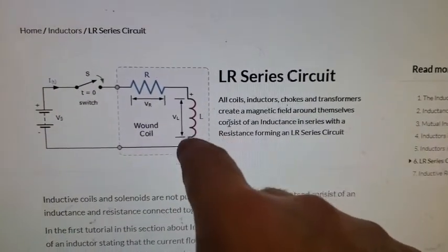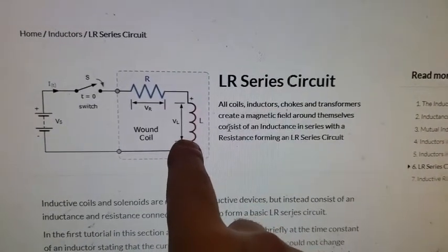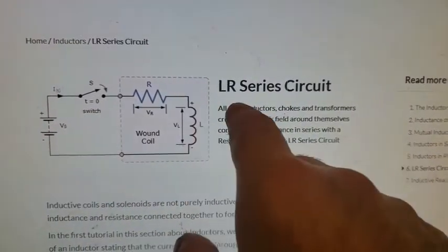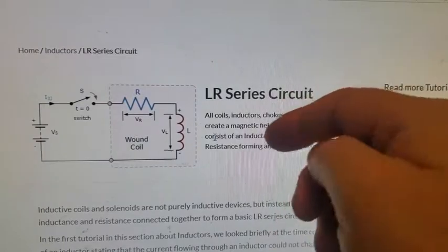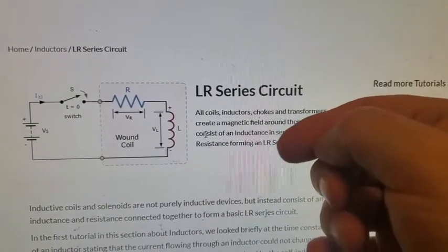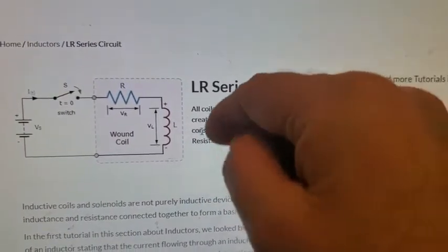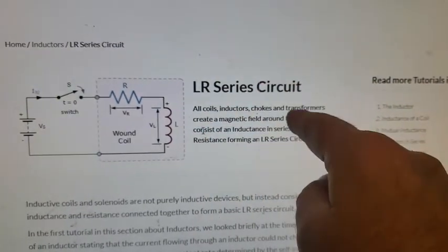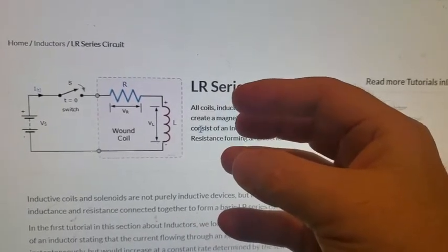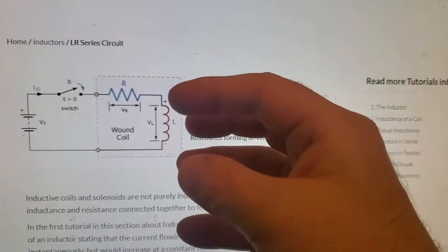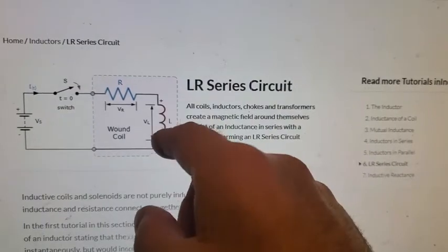So once again, to summarize, there is a dynamic resistance or a reactance to an inductor, wherein when you put in current, a magnetic field becomes established, and there is a magnetic flux associated with that field being established. That magnetic field, especially in a coil of wire where the current wavefront is passing through a wire with numerous adjacent wires around it, creates an induced magnetic field which opposes the flow of current.